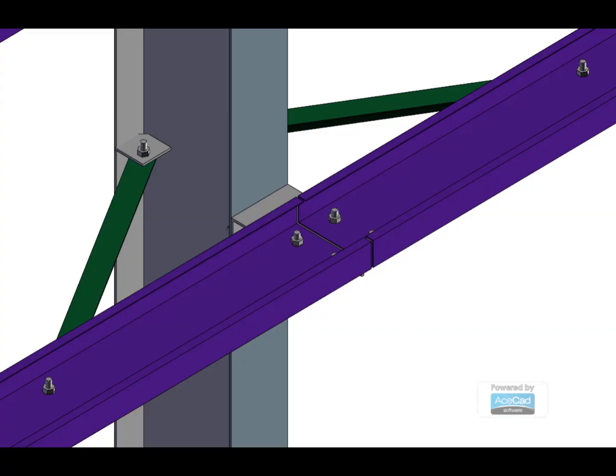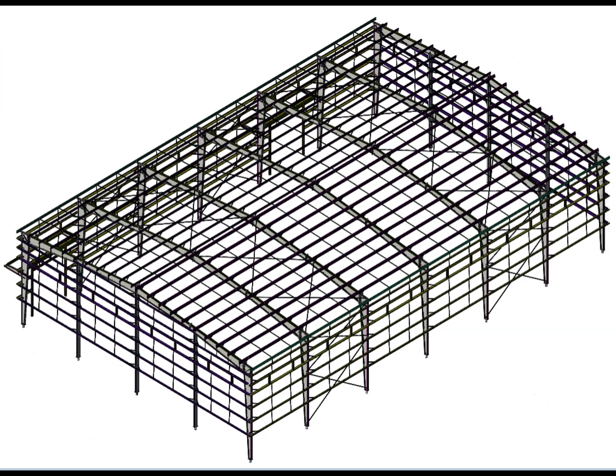So far, we have looked at the girt as an individual member and at its connections. Now let's step back and see the bigger picture. Complete picture. Look at the walls of the building. You can see the horizontal girt members extending through the wall framing system. Now compare that with what we saw in the individual connection details. The same member that looked like a simple horizontal line in the elevation is now visible as a complete three-dimensional framing system. This is one of the most important lessons when learning PEB drawings.